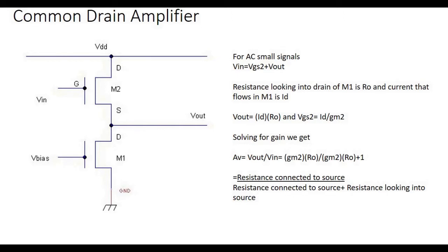The maximum current the NMOS source follower can sink is limited by the size of the current flowing in the current source load of M1. A source follower is a class A amplifier, where when discharging a load capacitance, the current through M1 limits the rate at which the capacitance can discharge.